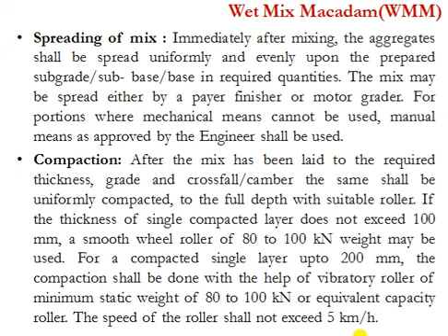So each pass of the roller shall be uniformly overlapped, and the grade and crossfall shall be checked, and any high spot or depression which becomes apparent should be corrected. The speed of the roller should be within 5 km per hour, and the rolling shall be continued till the density of the layer is 98% of the maximum dry density. The roller should not be used if the wet mix macadam layer is soft or yielding